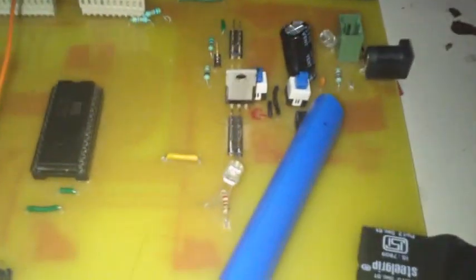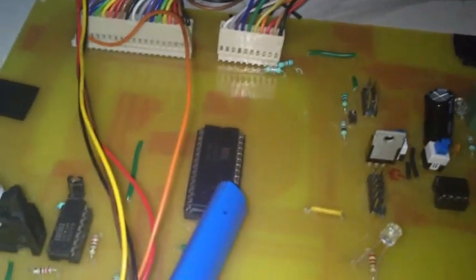All these sensors are connected to the PCB board, which is powered using a bridge rectifier. The board contains a 16x1 mux and a low-pass filter. The board is connected to the MSP 430 G2231. This in turn is connected to the server computer.